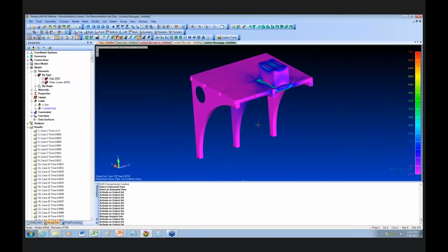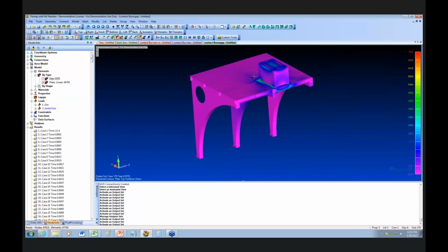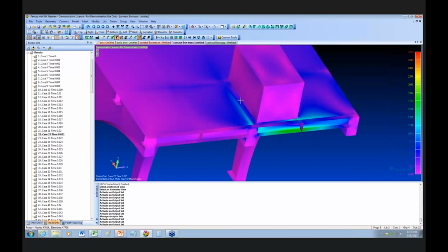So what this is simulating here is the nonlinear at contact, okay? This is the same model at contact as the transient. And in both ones, I use springs at the interface, and you have to use springs at the interface. It has to be connected together. So you can use bar elements.